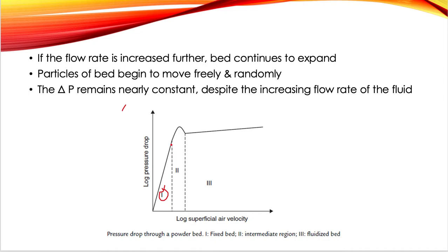This is because the fluid circulates, and this circulation velocity gradually increases. At low velocity, the bed will remain static and there are no changes in height or volume. Therefore, when the pressure drop is plotted against the air velocity, we get a straight line.